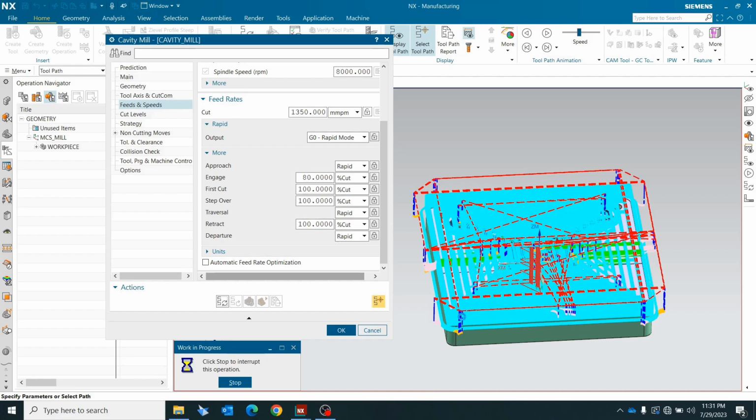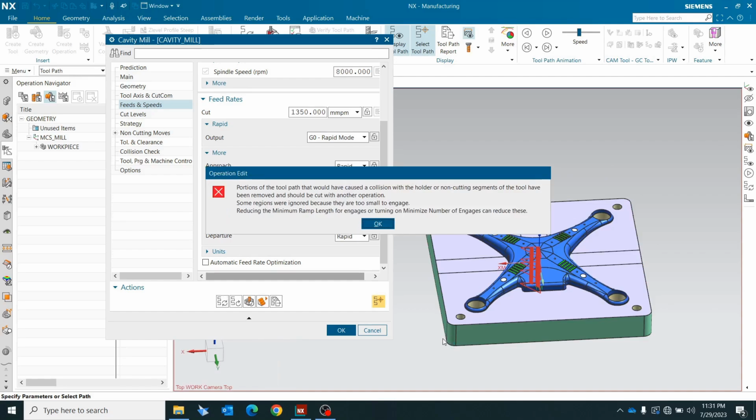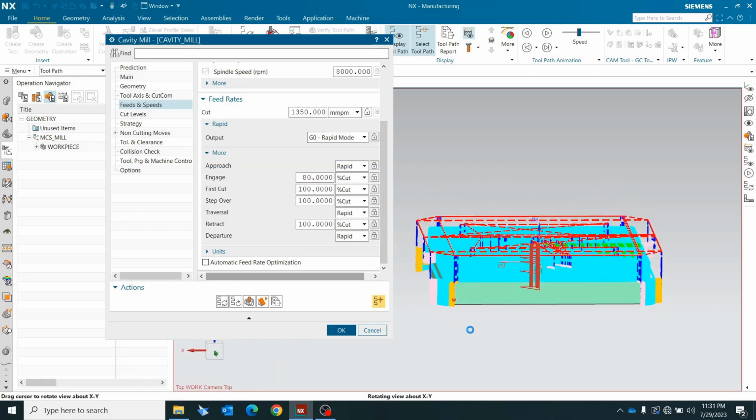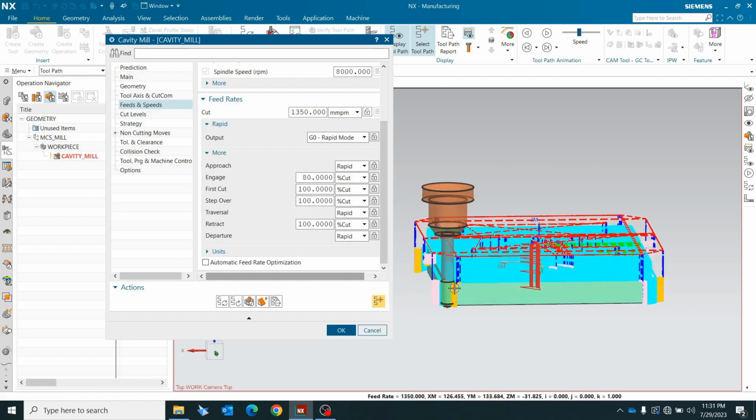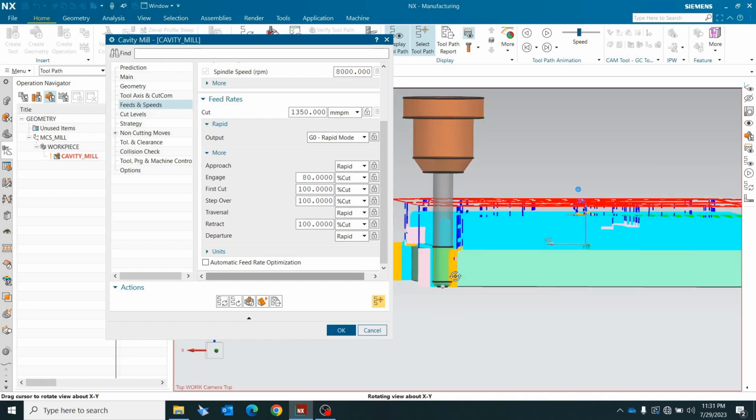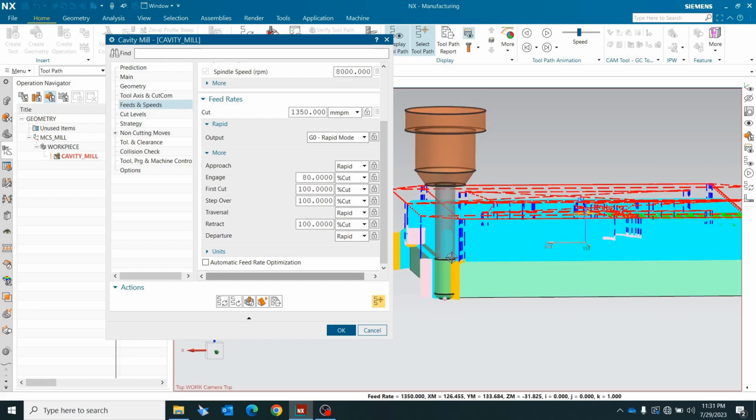Sometimes if you are having a limit like if you are having a tool length which is short, which should not go up to the depth. So short tool if you are having, then you don't want to go within a single setup up to the depth.